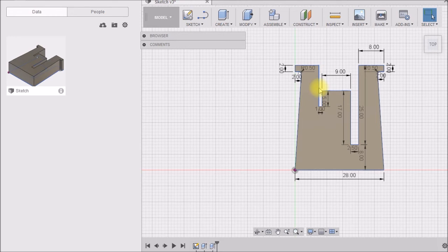And then there's also constraints that, for instance, this line and this line are parallel. When I tried to move this point in to taper the part, it wouldn't let me do that because this line was constrained vertical and that angle was constrained to be a right angle. So I tried to go in and delete as many constraints as I could see, but it just wouldn't let me do that. So I drew the part again, and this time I purposely drew this line not vertical. And then I was able to move it around because that line and this line were not constrained anymore.